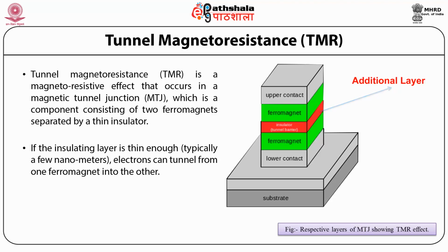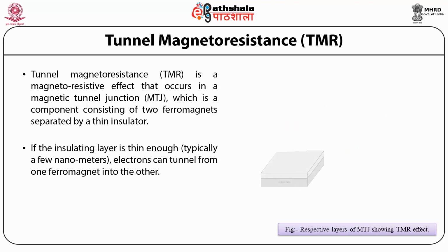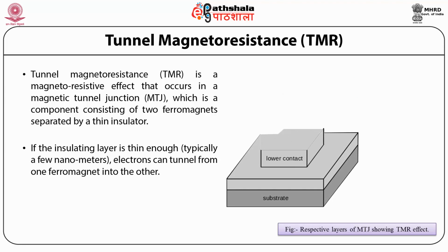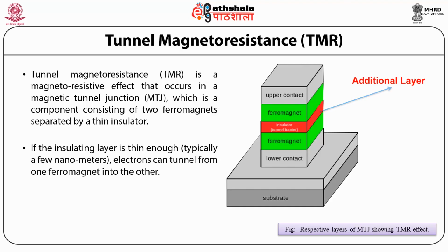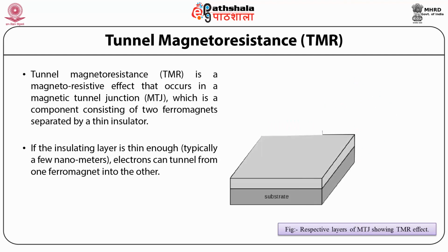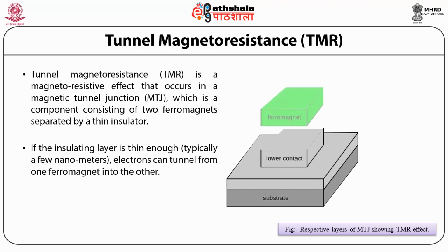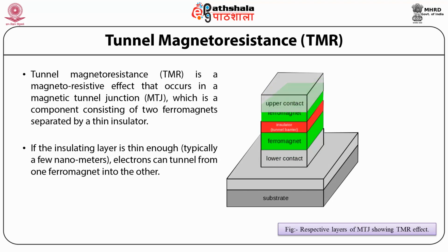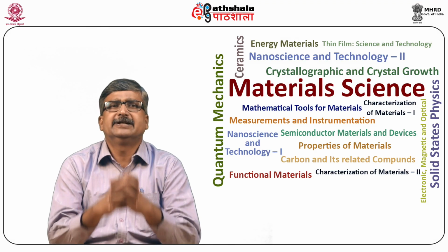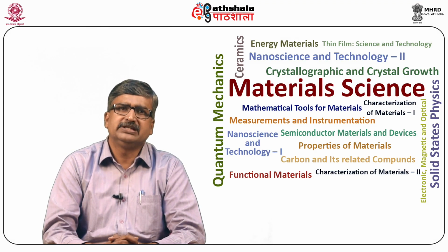Magnetic tunnel junctions are manufactured in thin film technology. On an industrial scale, the film deposition is done by magnetron sputter deposition. On a laboratory scale, molecular beam epitaxy or pulsed laser deposition is used. It is also possible by electron beam physical vapor deposition. The junctions are prepared by photolithography. Let us learn the basic phenomena of MTJ.